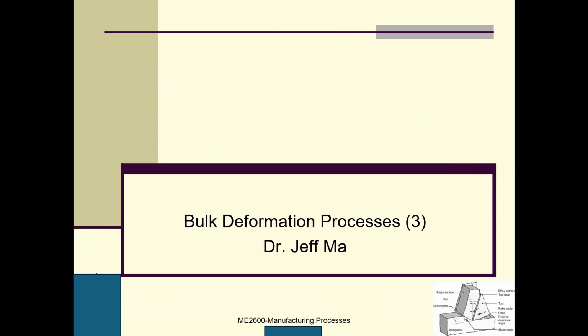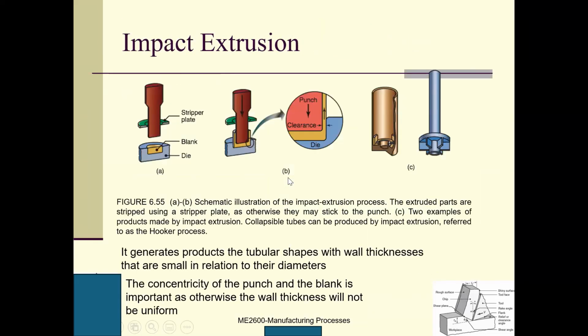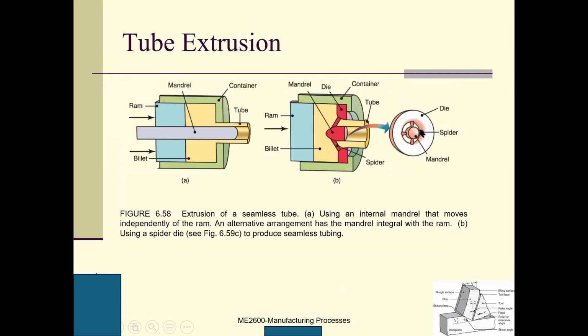Unlike the spider guys, once the material goes through, it remelts and welds together afterwards, it passes through like the bridge gaps. The spider die? Yeah. Spider die, this is here. So once it goes through those little bridges, the material reconnects afterwards and welds? Yeah, the material goes through this gap. This is orifice, this orifice, this orifice, and this orifice. And then it reconnects afterwards. Yes. Any other questions?